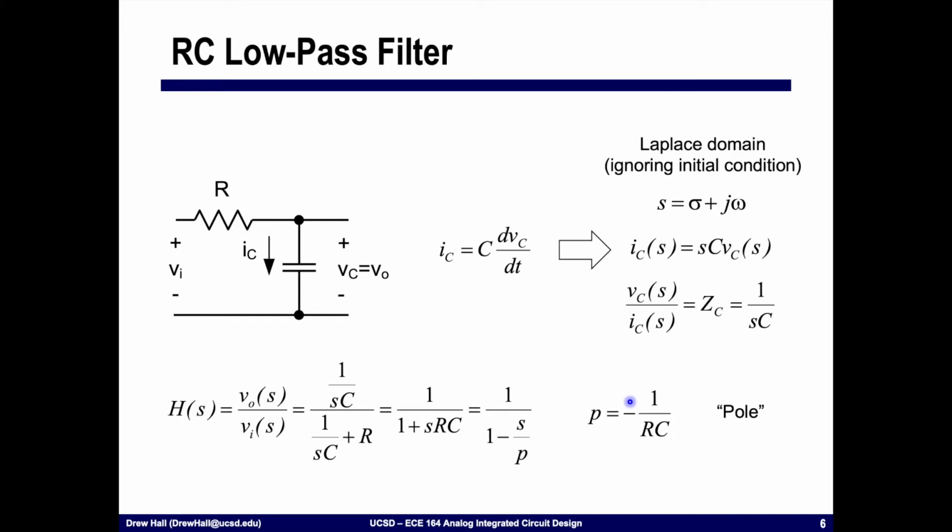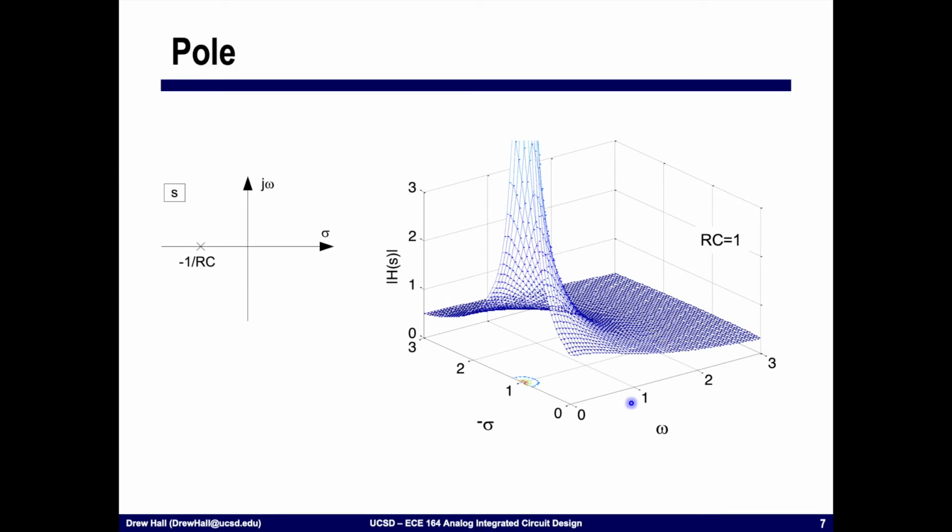It's a left half plane pole, which is going to give us a 20 dB per decade frequency roll-off. All right, so if we look at the complex plane here, we're plotting omega on this axis, we're plotting the gain on this axis, and we're operating right at the real axis.